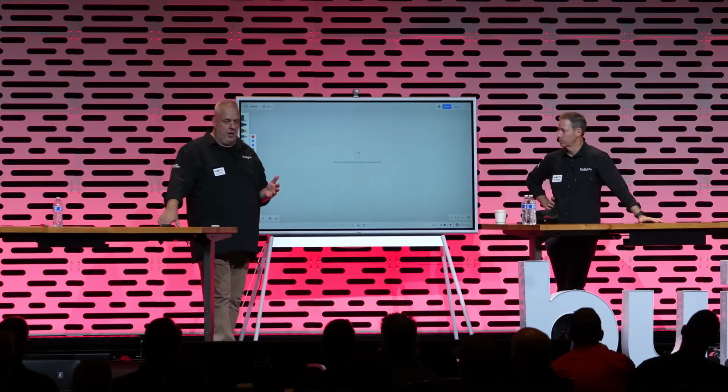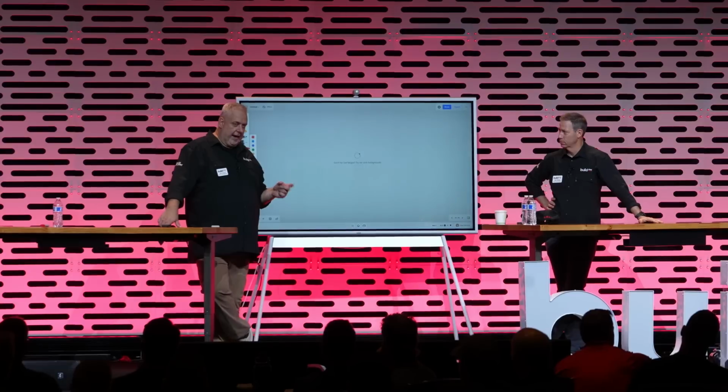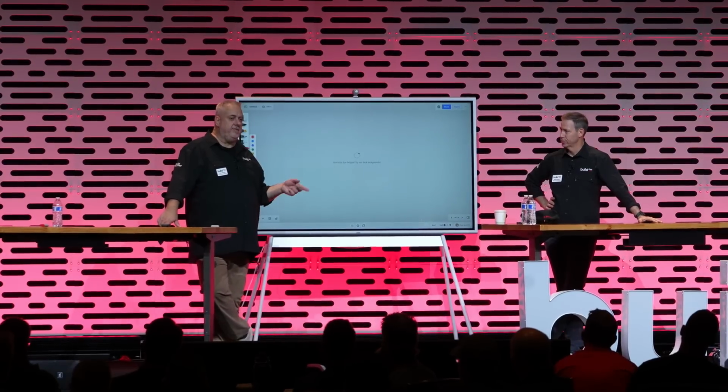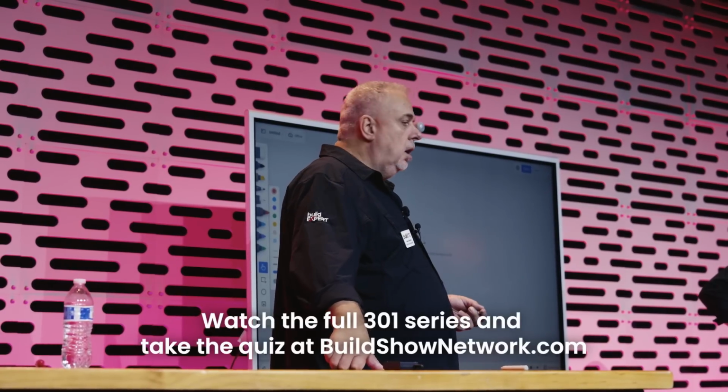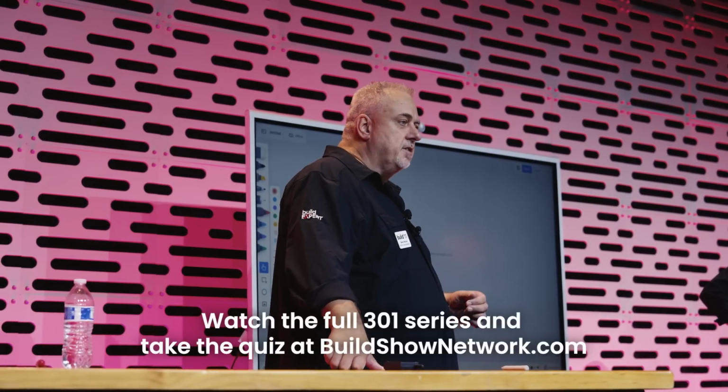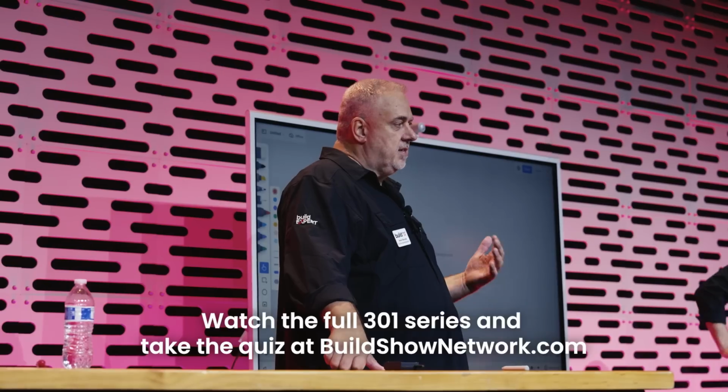And then we got to the point where I looked at him and said, "Mike, we're up to 8 inches of mechanically fastened insulation on the outside of the foundation wall." I said, that's ludicrous. I can't bring that to a builder. It's not executable, right? And that's one of the rules of details. We have to make sure that this is executable.